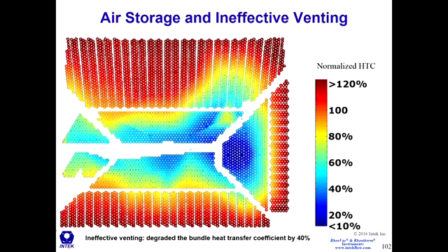Okay, so this is the performance profile. Again, this is not a model. These are direct measurements. This is a performance profile map created using temperature measurements. It's not a model. And so here is now the airbound zone and stagnant zone. They've joined together to make this massive area of blanketed tubes in this particular condenser.